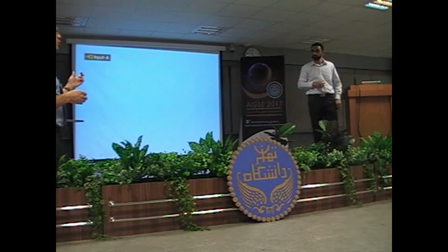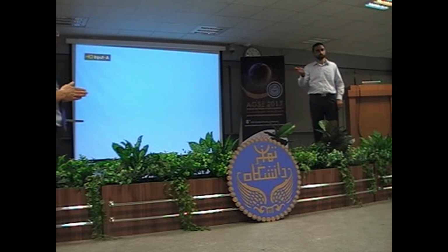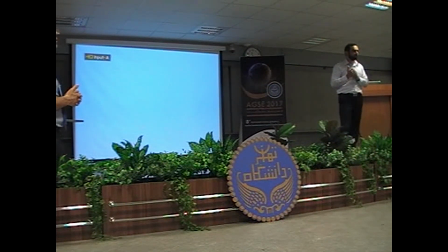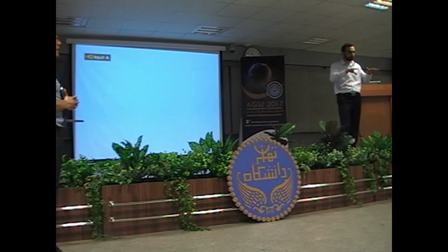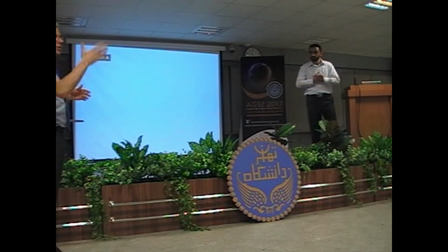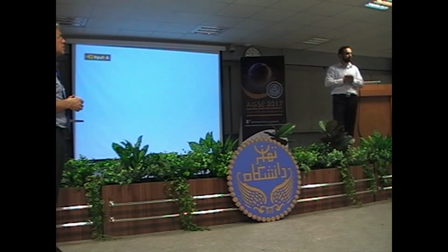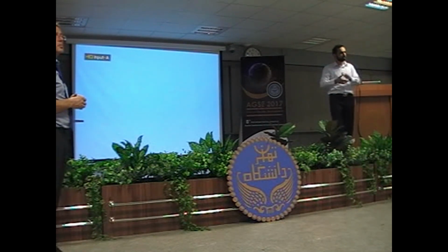But from the amplitude, could we derive the amount of moisture? You can apply change detection scenarios, but not using interferometry. You use the amplitude information, not the phase. The phase is not impacted by the soil moisture difference at two different times. Has there been any research regarding this? Yeah, there is a lot of research on calculating the changes that are happening, for example before and after a time, but this is based on the amplitude, not the phase.